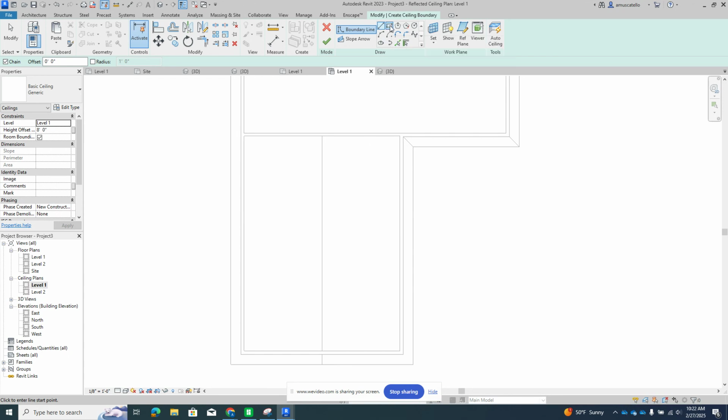I'm going to select rectangle, click on the interior part of my wall, move my cursor up to the ridge line and select that midpoint. And now it has placed a pink rectangle on the left side of our roof.